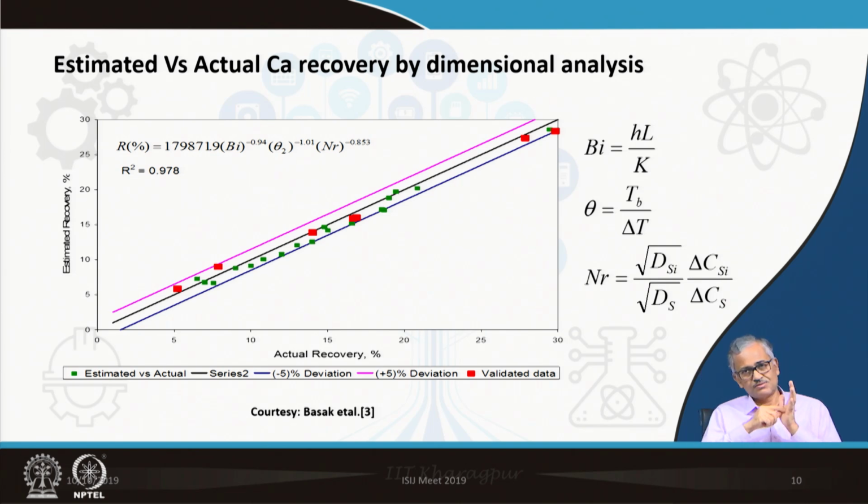But if the silicon transfer from the powder to the bath is much faster, then as the silicon gets depleted from the powder, the calcium activity will increase and its vapor pressure will go on increasing. So, if the silicon transfer is much faster compared to the sulfur transfer, and the sulfur comes and combines with the calcium, that is a much stronger compound, and in that case the activity of calcium will not decrease, because silicon is leaving but sulfur is coming and combining with the calcium forming calcium sulfide, and that can be retained.